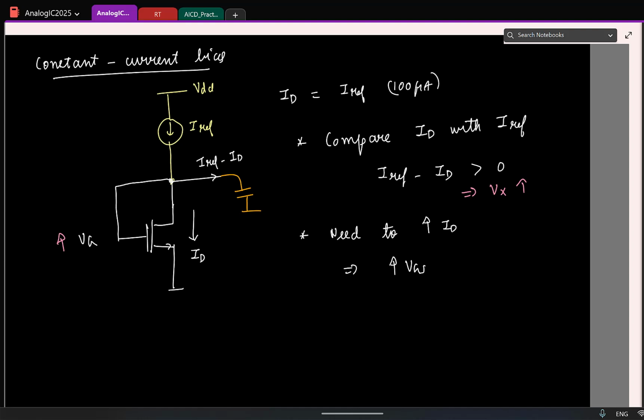And some jargon. This we typically call a diode-connected transistor. So maybe sometimes I'll use this term, diode-connected. Again, this has historical reasons. It turned out, 40 years back when the transistors were bipolar junction transistors, the moment you made this connection, that effectively became a diode. So people called it diode-connected. But with MOSFET, that's no longer the case, but the name just stuck around.